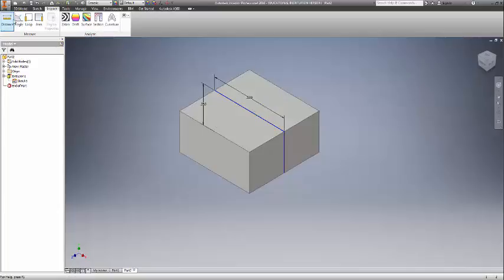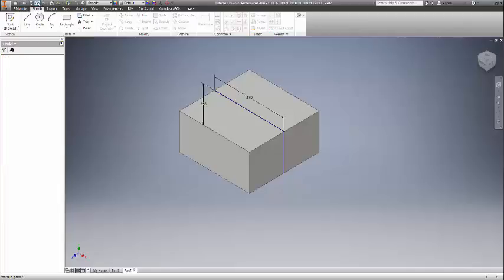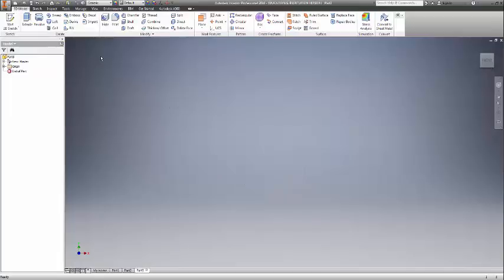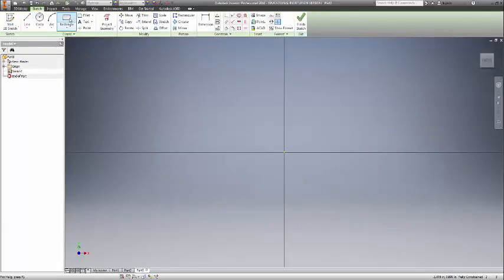Okay. You can also do angles. If you have a curved surface, you can do that. All right, so let's go back. Let's do File, New Part, and let's do something different here. Let's make a box. So let's do a 2D sketch. Okay, we're going to click on the front, and I actually want you to make this one. We're going to click the front surface here. Let's do a rectangle. I'm going to start it right in the center, bring it up and over, and we're going to do 1 inch, tab, 1 inch, enter.